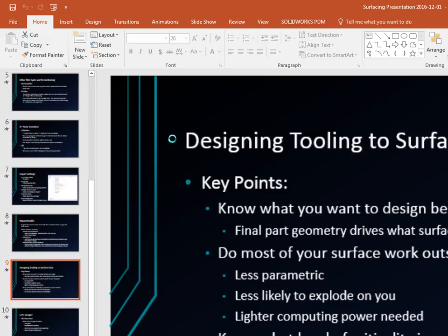For example, if you were to create another surface in your other sketch that was like a dome up above it, you could do replace face with the one surface with the other, which would create that as a dome. So if you were to go back into your main part and simply create a whole new surface above the bottom, I think you can do replace face at that point.